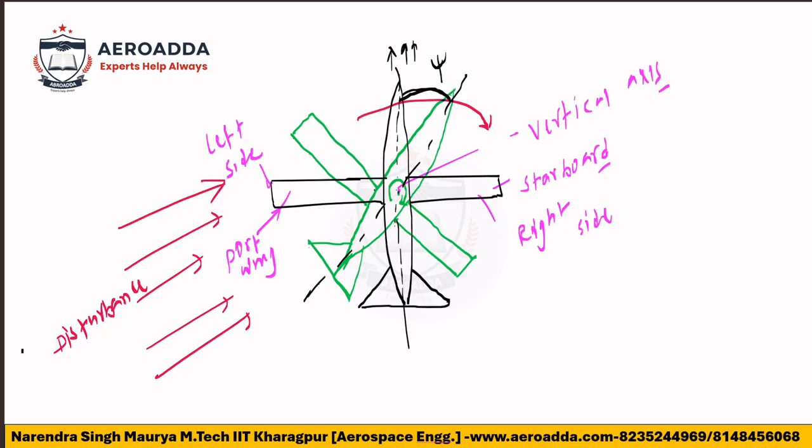Everybody, please. So now, to make it stable, this aircraft about the vertical axis should have a restoring moment, and that restoring moment is nothing but, see, it is yaw in this direction. It is because of the disturbance. It is yaw in this direction. To restore its original position, there should be a yawing moment.